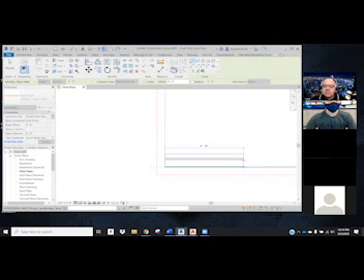If I press my space bar, I'll flip the wall. So everybody try and flip a wall using your space bar. Whatever direction you go, you can flip the wall with the space bar and just keep going. But you need to pay attention to what the interior is versus the exterior.